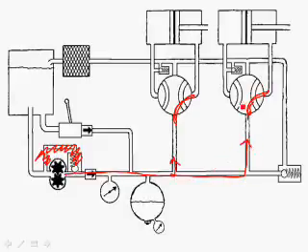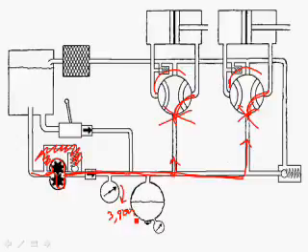Let's say all of a sudden we stop, we turn the selector valves to the off position, and we don't let any more fluid come into the actuators. Well, the fluid is getting pumped from the engine-driven pump into the system, and if all of a sudden we turn these off, the pressure is going to go too high. Maybe it'll go up to 3800 psi. And maybe that's a little too high. We don't want the pressure to get that high.